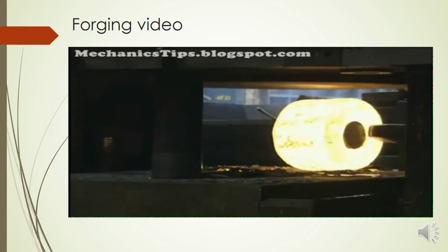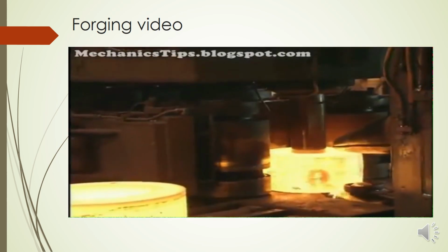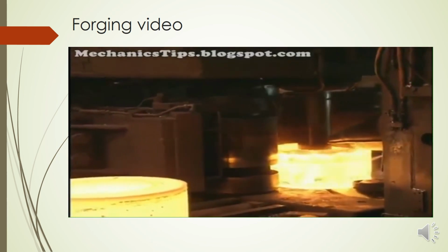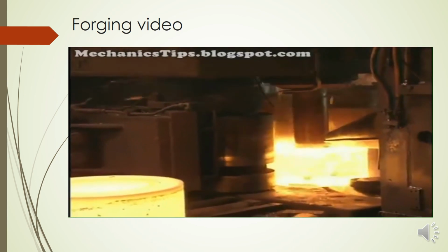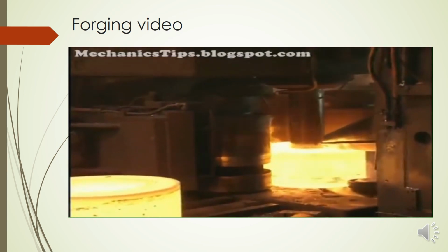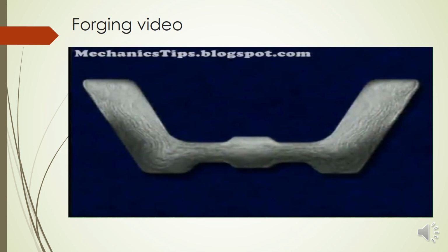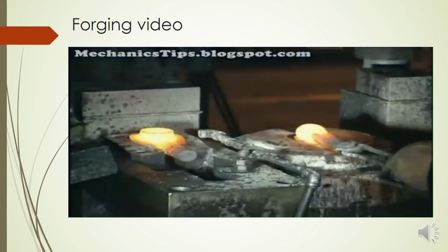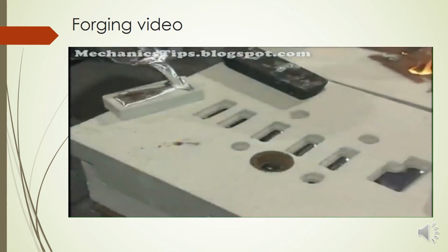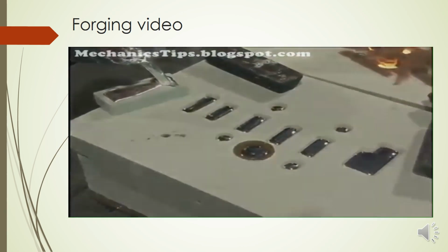So all these parts are hot forged to near net shape and to form discrete parts, because it is from these heated wrought mill forms, from the furnace, that we are forging the parts, further refining the microstructure and the directional grain flow. Because of these effects on microstructure and grain flow, the mechanical performance of wrought mill forms and hot forging parts is typically superior to that of cast metals.